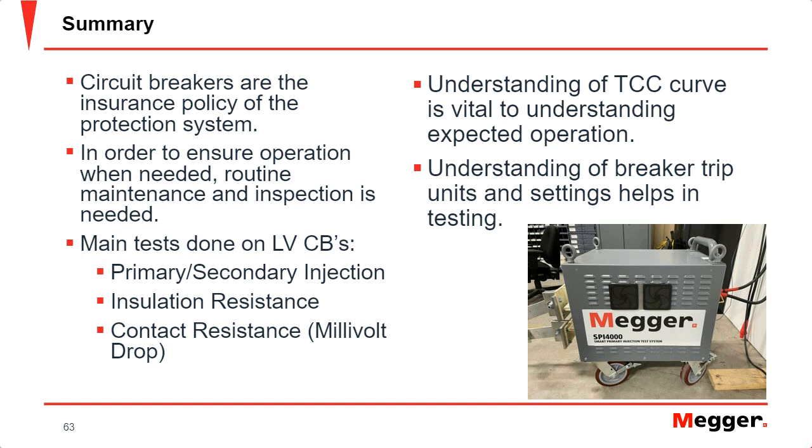The biggest hurdle is understanding those time current curves. In order to actually test the breaker correctly, you have to be able to read those curves. And then just understanding the breaker trip units, how to find your test current, everything like that, can go a long way as far as testing a breaker in 5 to 10 minutes versus 30 minutes to an hour a breaker, right? Just the understanding of it.